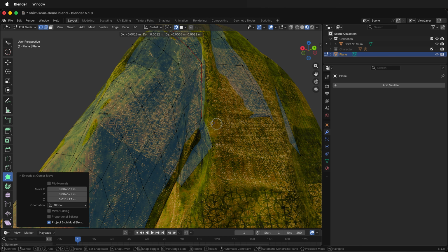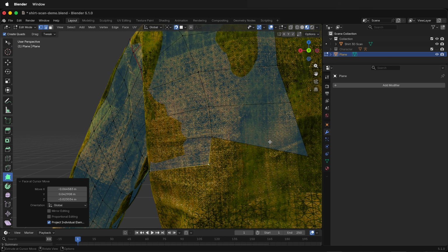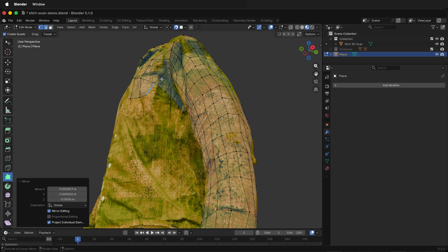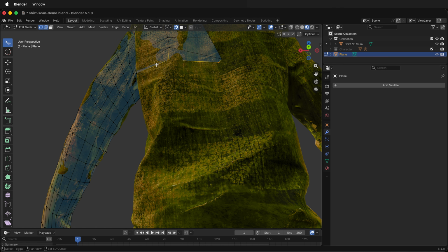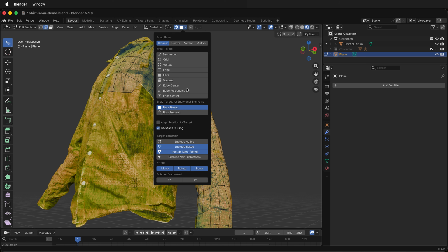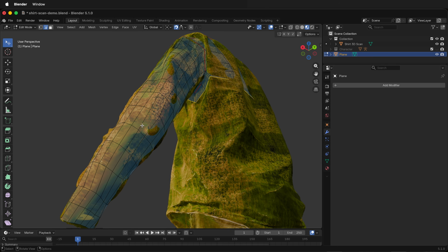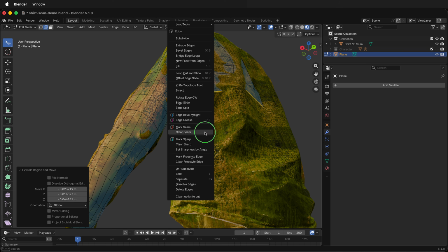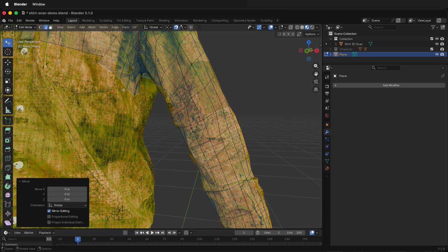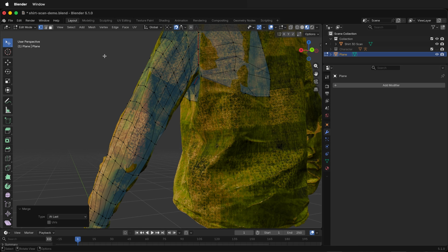And then I can bring this one over. I think that looks pretty good. And then just come right over to there. Here I have one extra panel depth. So I'm just going to press 2, select these edges as I go around here. And then I want to switch from face project to face nearest. And then press E, just extrude down a bit, right click LoopTools Relax, G to move. And now that's pretty straight right there. I can maybe just move it up a little bit. 1, and then I'll merge these vertices, ML. And then over here, that should all be fine.